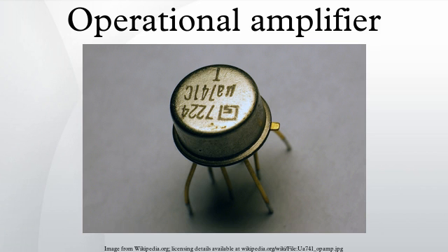The potentials at the operational amplifier inputs remain virtually constant in the inverting configuration. The constant operating potential typically results in distortion levels that are lower than those attainable with a non-inverting topology. Other applications: audio and video frequency preamplifiers and buffers, differential amplifiers, differentiators and integrators, filters, precision rectifiers, precision peak detectors, voltage and current regulators, analog calculators, analog to digital converters, digital to analog converters, voltage clamping, oscillators and waveform generators. Most single, dual and quad op-amps available have a standardized pinout which permits one type to be substituted for another without wiring changes.